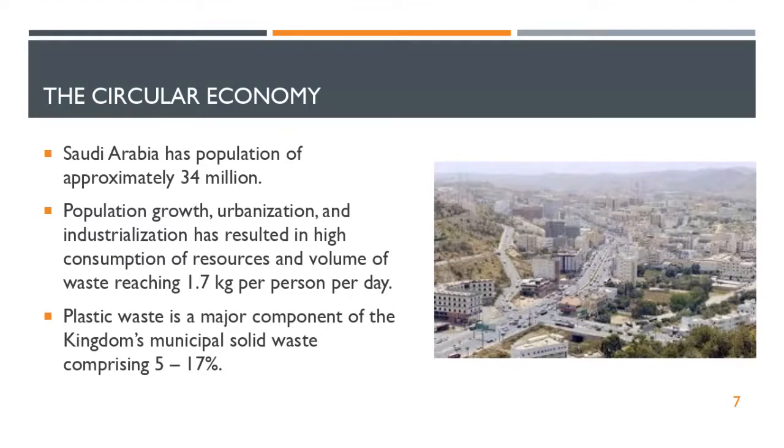So it's observed how it is deforming or not deforming, and also core samples are taken at periodic places to see what the composition of the layer is itself, how it is performing. So it's both a lab and also a visual testing.